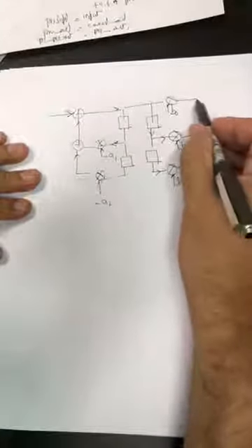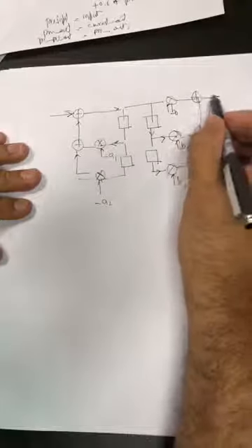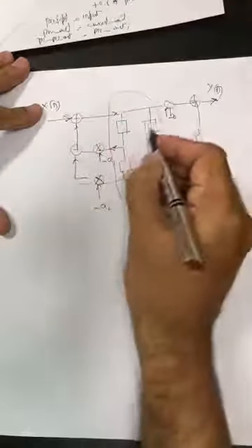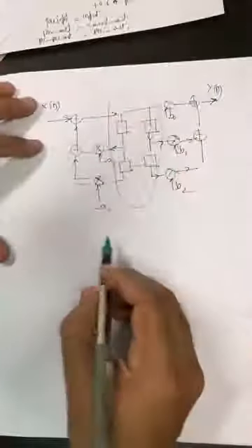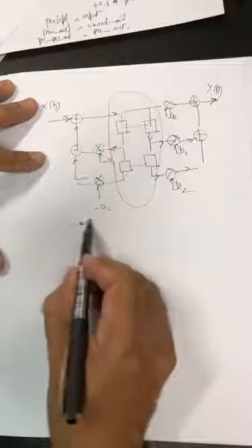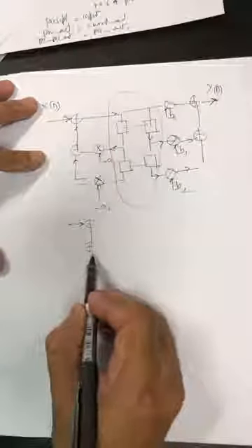So this is the filter. You put an x[n] here, you get a y[n] here, and then you realize that here you are wasting storage because this is the same as this, which is the same as this. So why not collapse them and make it into a filter like this.